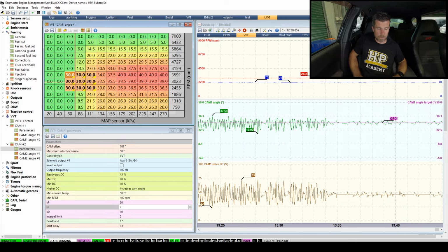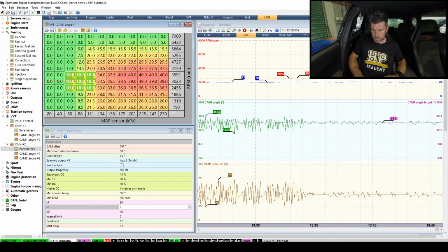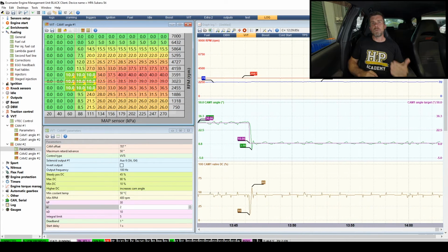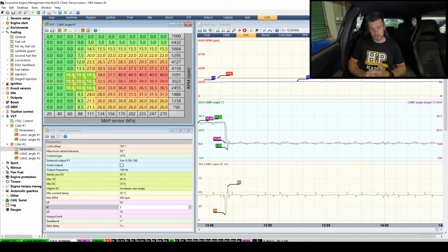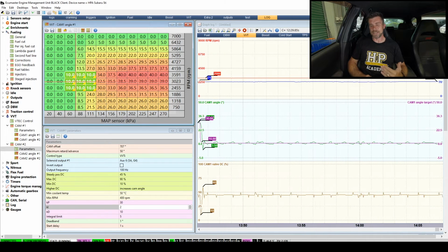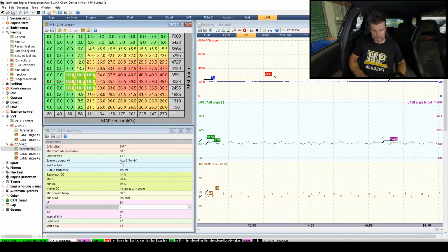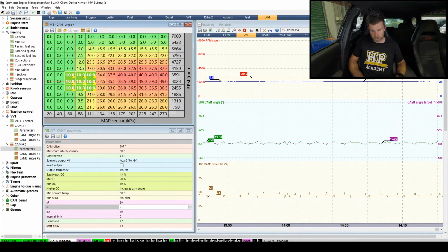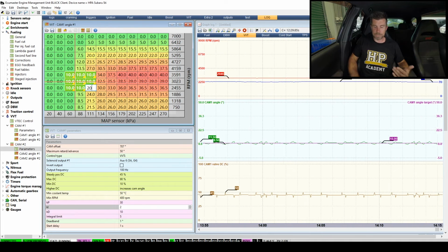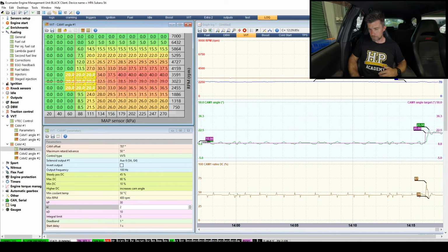Let's just try a few more steps, and we'll go back down to 10 degrees. We'll now make some smaller step changes because, as I've mentioned, 20 degrees is a larger step change than we ideally would want to see instantaneously. So let's make a 10 degree change. We'll go from 10 degrees up to 20, and we'll have a look at our response.